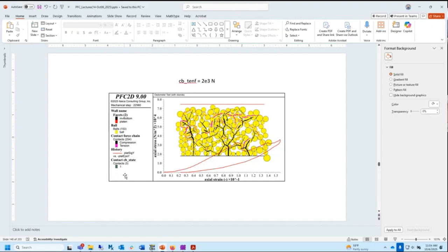No, I mean in general. Well, in this case, we gave infinite shear strength, so the only way it can fail is tension. So we should never get a state of 2, okay. And so what would need to be done here, again, it's a vast microstructural space. You could then say, let's set tension and shear equal, and see what happens. Let's set tension infinite and just shear. If you set tension infinite and just shear, you're going to make it behave like a metal. It's not going to behave brittly like a rock like this. It's going to have plastic deformation. It's really crazy.